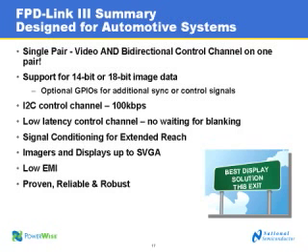It has low latency control channel, no waiting for the blanking, and as well it has a lot of the features that really have been defining our product family from the beginning. Signal conditioning for extended reach. In this case, because of the pixel clock frequency, it supports up to SVGA for both imagers and displays. And like we mentioned before, very importantly, these are low EMI solutions. They're proven, reliable, and robust for automotive applications. Another question that came in, how about multiple cameras sitting on a single link and you need to select which stream comes across? Yeah, so each camera will have its own independent link. So that really, I guess, kind of answers the question: each camera will be assigned to one serializer, deserializer pair. Okay.